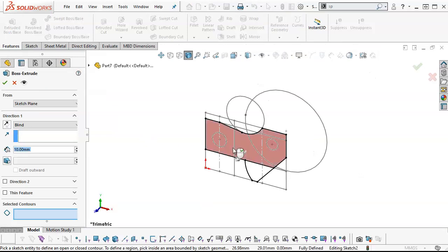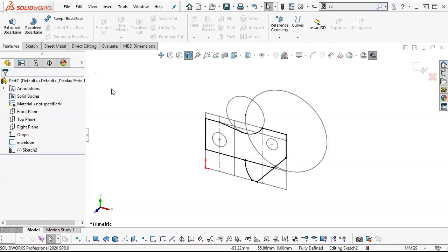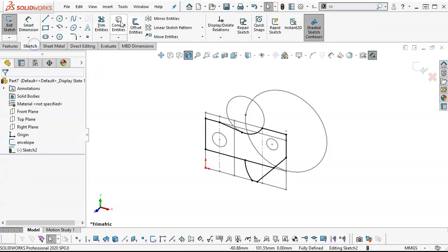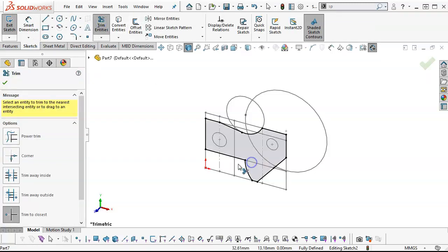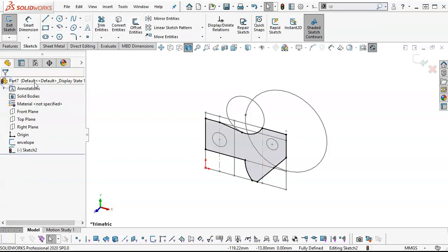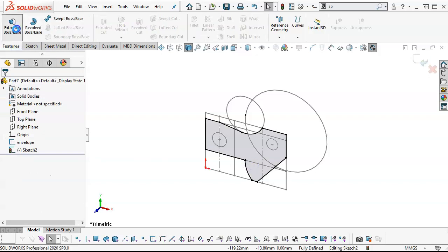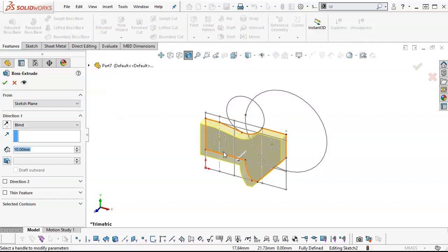I'm going to drag it in that direction. Oh, we ended up with an extra, so I didn't quite get it all trimmed out. That'll put me back into the sketch if I just X out of it. Alright, I'll try one more. Kind of go to all that trouble to trim, I'm really expecting to see it go right into the preview of the body.